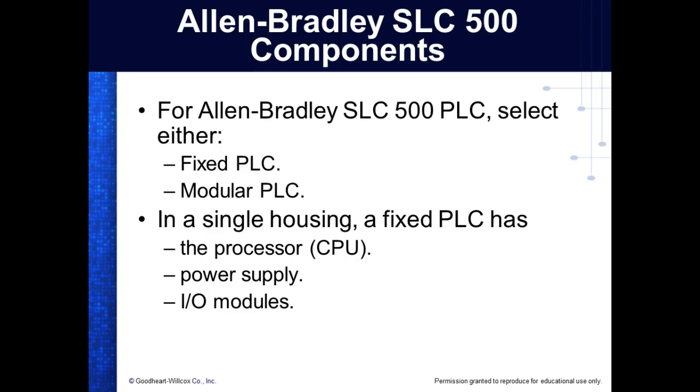So a fixed PLC, you get what you buy, right? You understand that. A modular PLC, you can upgrade it, you can get what you want. Single housing fixed PLCs, the processor, power supply, and I/O module is usually all in one unit. And this is kind of different.